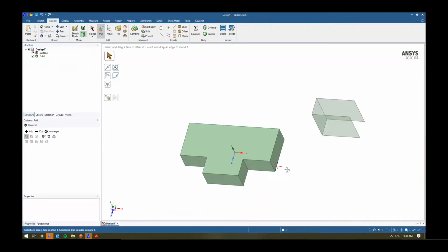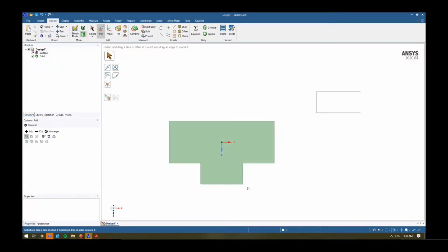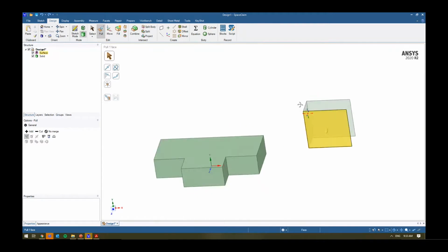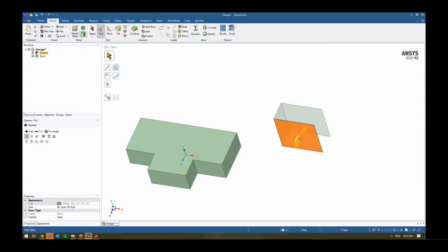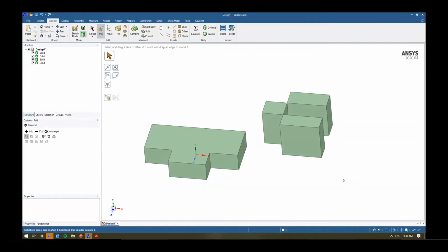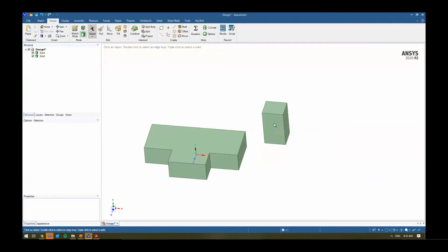So you'll notice it's very flexible in the way that you can do it, right? I didn't need to go back to the sketch and make a bunch of changes and align this wherever I wanted to. I can just pull and push on some of these components and make them bigger or smaller as well. I was able to use that line to create a surface, and then again, similar to before, I can use a pull feature and pull onto that as well and generate some of these surfaces, right? And you'll notice it creates multiple solids. Right, I'll just delete those off.